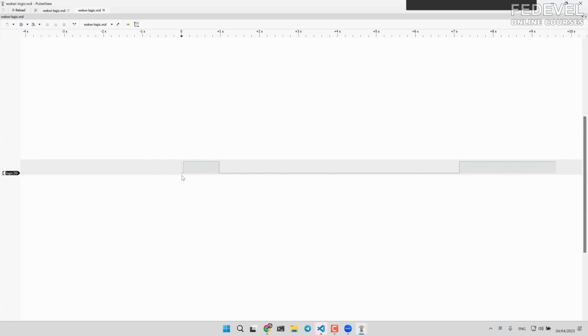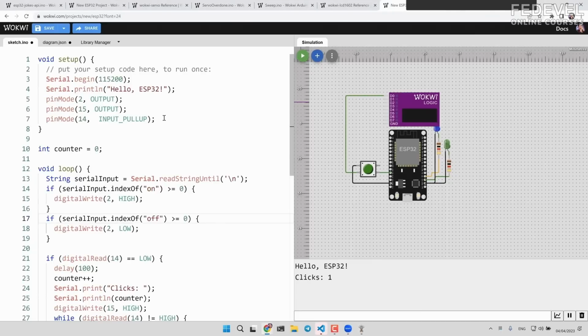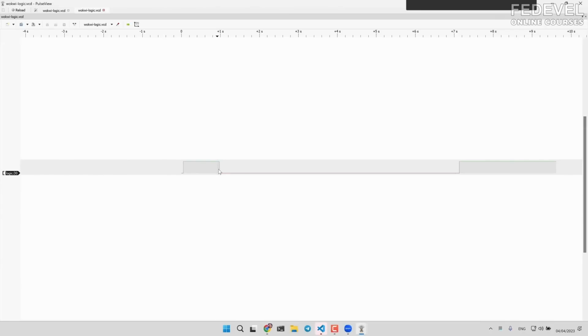So at the beginning, this is when the simulation started. At this point, when we zoomed in, the transition was very smooth. This is when we turned this button into a pull-up. Enabled pull-up, yeah. And this is when we pressed the button, because you connect it to low. Exactly, and this is when we left the button, we released it, right? We can actually see how much time